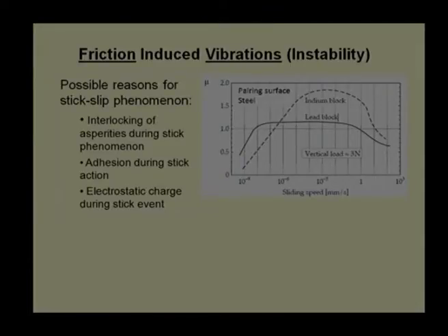speed domain. If you are operating the machine at a very high speed domain, some other instability comes, and in that case friction instability does not come. But in low speed operation, friction instability is dominant and we need to cure it. We need to avoid it, either using an active control system or some lubrication mechanism.